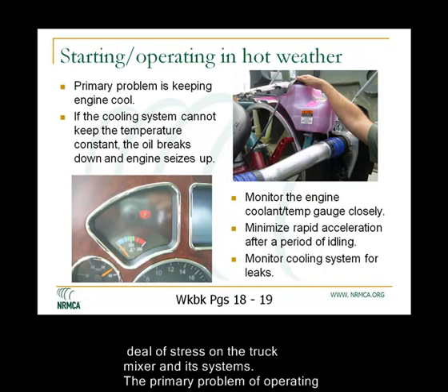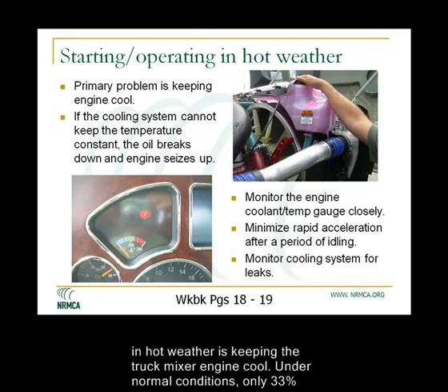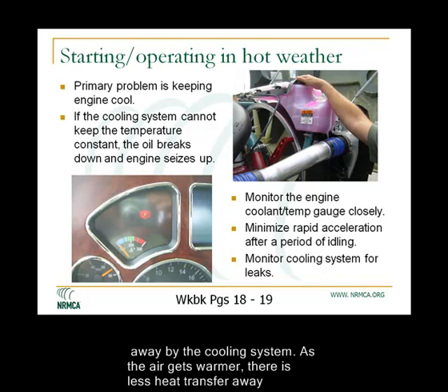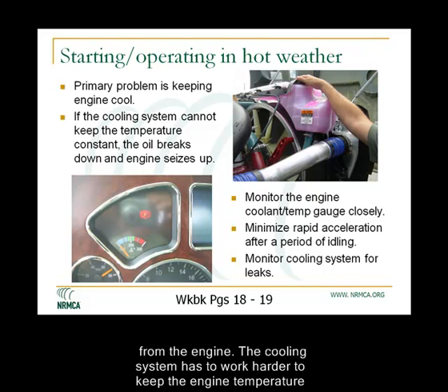The primary problem of operating in hot weather is keeping the truck mixer engine cool. Under normal conditions, only 33% of the heat generated by the engine is used as horsepower. The rest has to be carried away by the cooling system. As the air gets warmer, there is less heat transfer away from the engine. The cooling system has to work harder to keep the engine temperature constant.